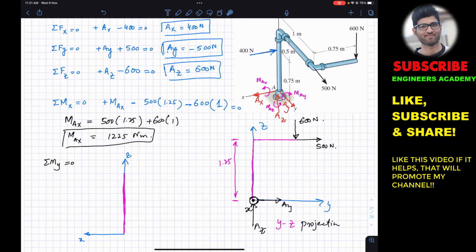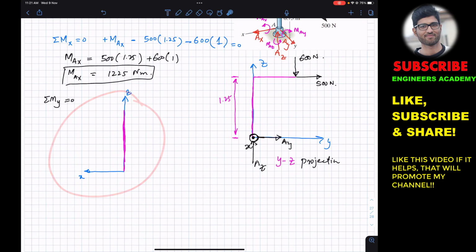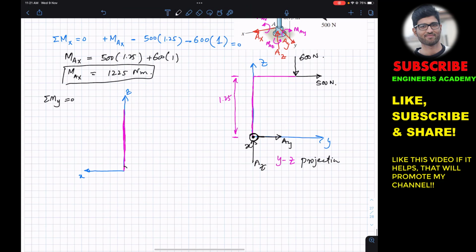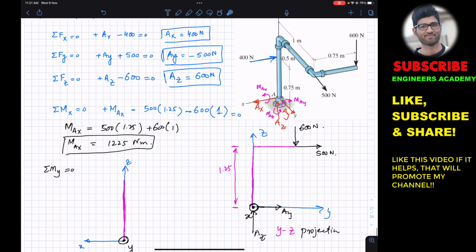And then this portion of the pipe is towards the y-axis, and in this particular free body diagram, in this particular projection, the y-axis is out of the screen. So let's show that the y-axis is out of the screen. Now in this diagram, we cannot show that the pipe is out of the screen since it's a 2D diagram. So we will directly draw this part of the pipe, and this part is towards the negative axis. So we will draw it here. This is 0.75. So we will have 0.75 like this.